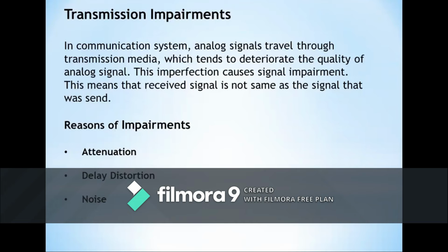Last type of noise is impulse noise. All the types of noise discussed so far are reasonably predictable and their magnitude is relatively constant, so it is a bit easier for the system engineer to deal with them. But impulse noise is completely different from the other types. It is non-continuous by nature and is made of noise spikes of short duration and high amplitude. These noise pulses occur irregularly and they are extremely unpredictable.